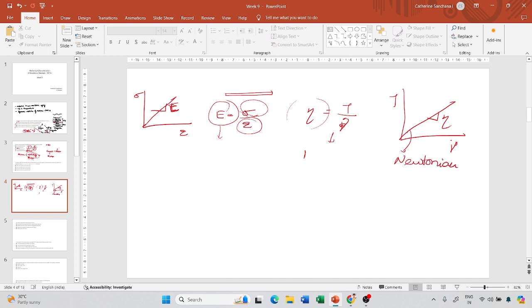Okay, so no matter what the shear rate is, your viscosity is going to remain the same, right? Now in mixing and compaction temperature, in mixing they are targeting a Newtonian behavior, because there are aggregates and there is your bitumen, and when you try to mix the aggregates and the bitumen, there's going to be shearing, okay, at the interfaces.